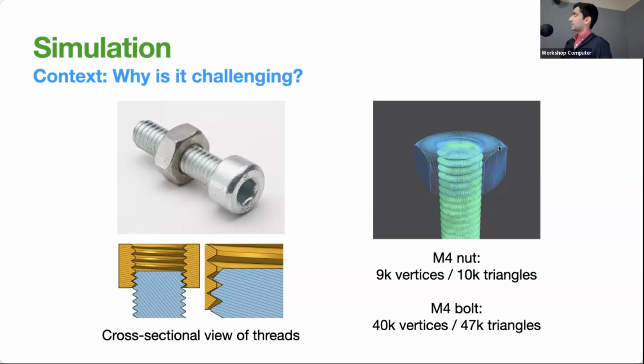Furthermore, accurate triangular meshes of the nut and bolt may consist of over 50,000 elements. It's a major computational challenge to detect collisions between these meshes, generate contact points and normals, and solve non-penetration constraints. As a result, the fastest general-purpose simulators could only simulate a nut and bolt between 1/80th and 1/20th of real time.